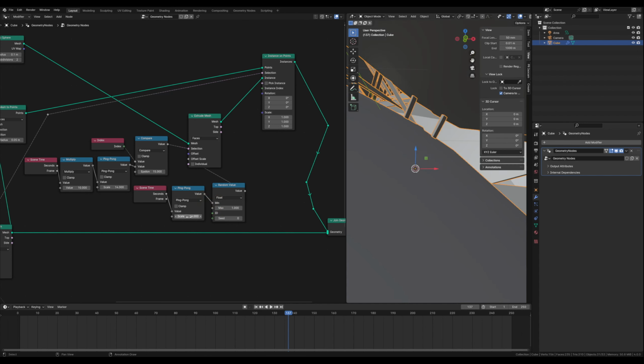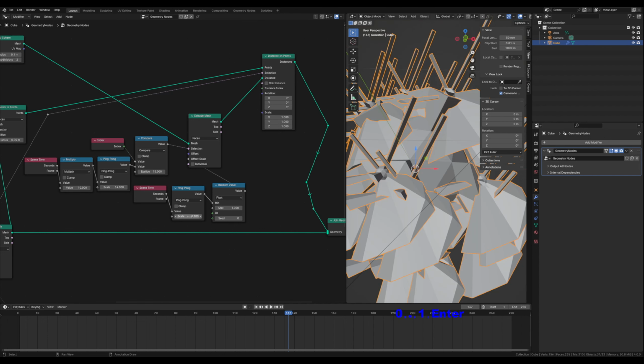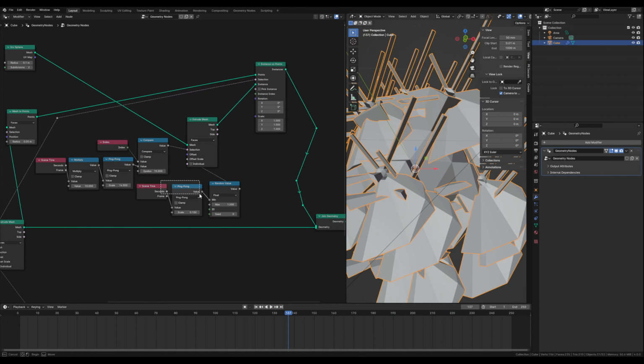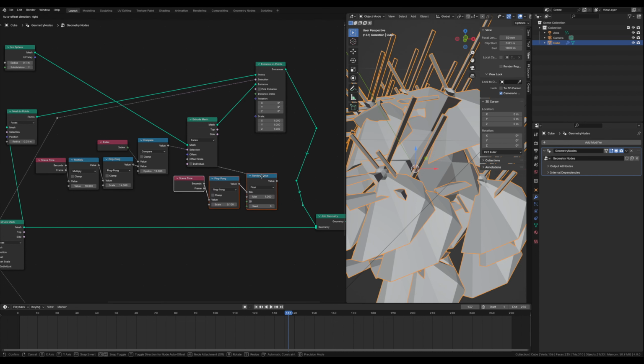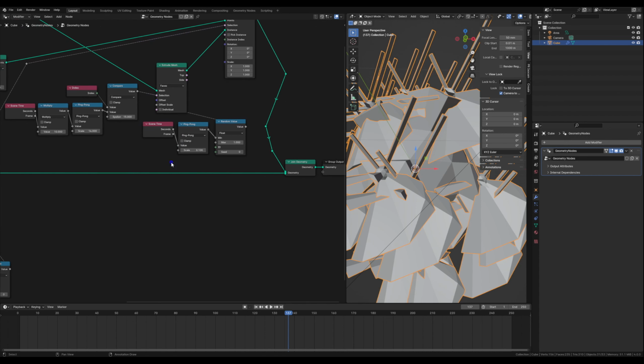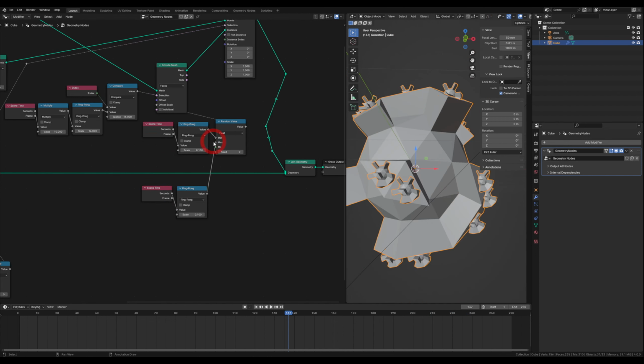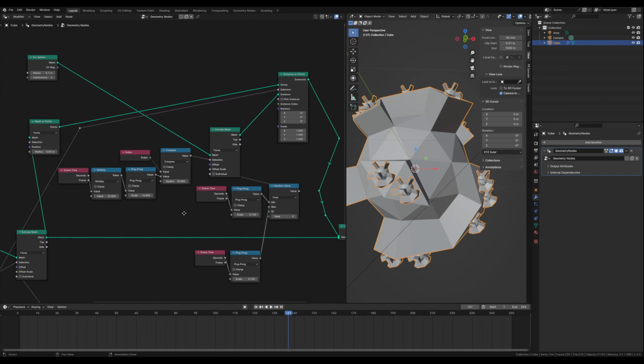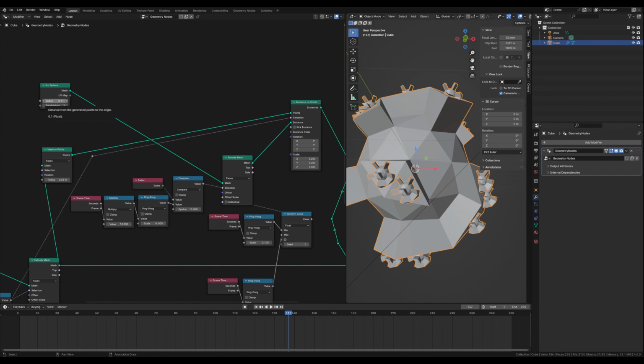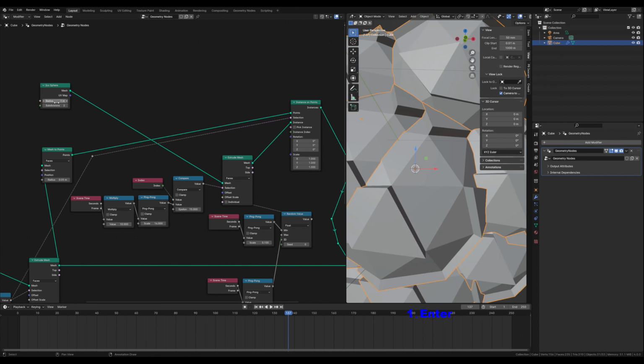Okay, and let's change the scale of this to maybe 0.1. Okay, and the second value, maybe we want to duplicate this, Shift D, and connect to the second value, and let's change the scale of this to maybe, okay, let's leave it for now, and we want to change the radius of our icosphere to maybe 1 point.